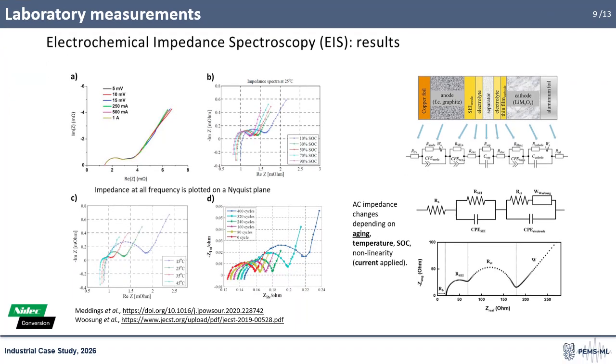The electrochemical impedance spectroscopy characteristics depend on 3 key factors: temperature, state of charge, and aging. In fact, lower temperatures imply higher resistance due to the uneasiness of chemical reactions because of lower thermal energy. In general, the resistance reduces at higher states of charge. Moreover, aging plays an important role in resistance. As the cell degradation proceeds, the resistance increases.